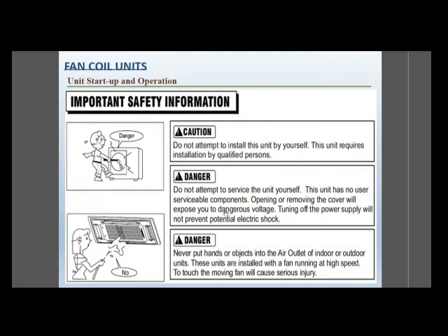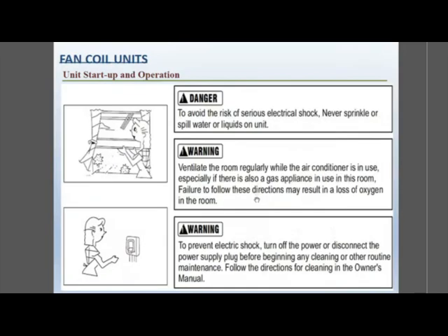Never put hands or objects into the air outlet of indoor or outdoor units. These units are installed with a fan running at high speed. To touch the moving fan will cause serious injury. Fan coil units. Unit startup and operation. To avoid the risk of serious electrical shock, never sprinkle or spill water or any liquid into the unit.